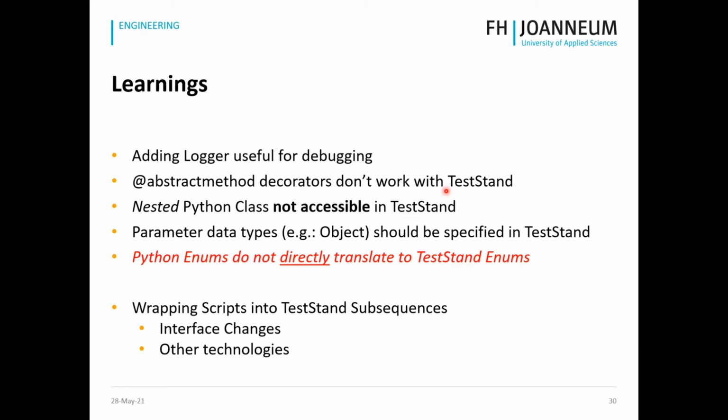And if you nest Python classes, we tried that with enumerators, they sadly are not accessible in TestStand as far as I could tell. So we had to take our enumerators and put them outside of our classes, which is no problem, but it's just important to know because that might be a roadblock for developers.